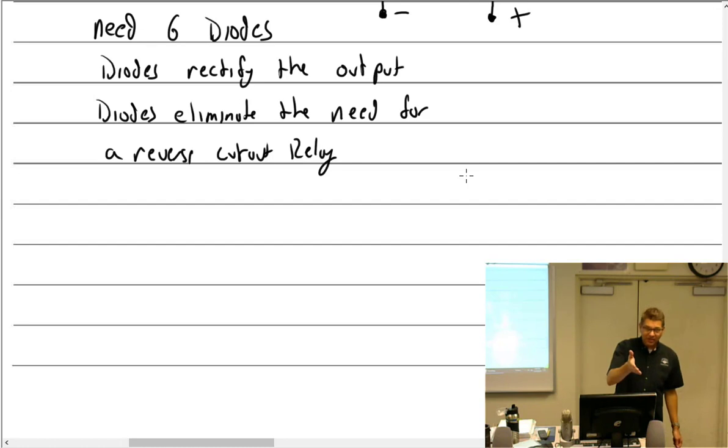Checking the, what was the other thing? The drive belt. What are you looking for in the drive belt? Racks. Beautiful. Tension. Just throw tension. What should the tension be? Depends on the manufacturer. Whatever the manual says. That's exactly it.